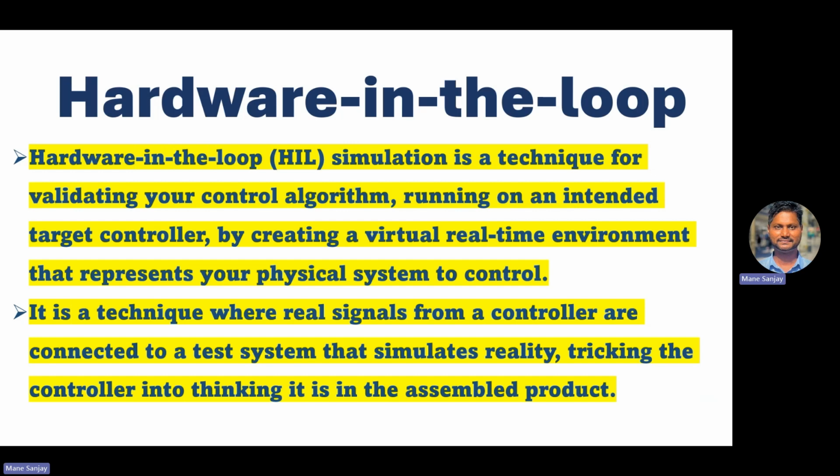That's the beauty. In hardware-in-the-loop simulation, you fool your ECU that it is actually connected to the vehicle or the product by simulating its environment. Environment means you are simulating its inputs and outputs. If there are a few sensors, you simulate those sensors with the help of a real-time simulator.